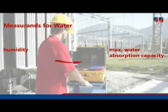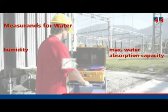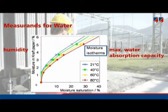To convert one measure to the other, the so-called moisture isotherms can be used. In the graph shown here, on the left-hand side can be seen moisture content, and on the bottom, relative saturation. By observing the temperature, the user can go from one measure to the other. For example, 10% relative saturation at 20 degrees Celsius means 3.5% moisture content. So, one measure can be calculated from the other and vice versa.